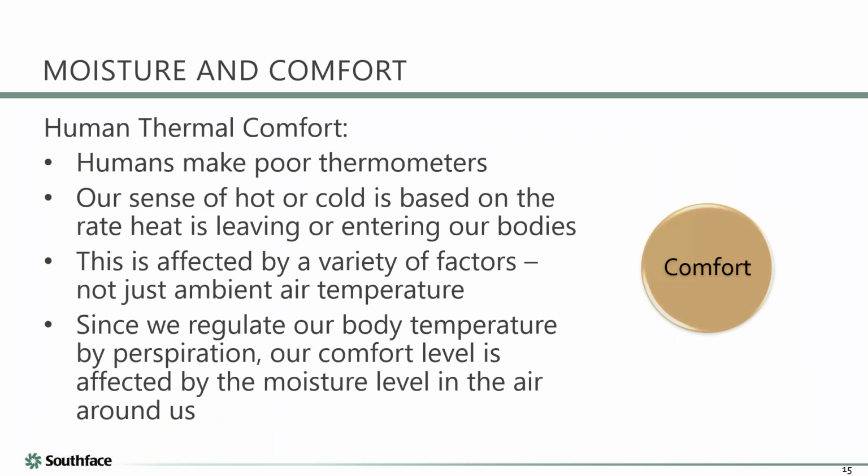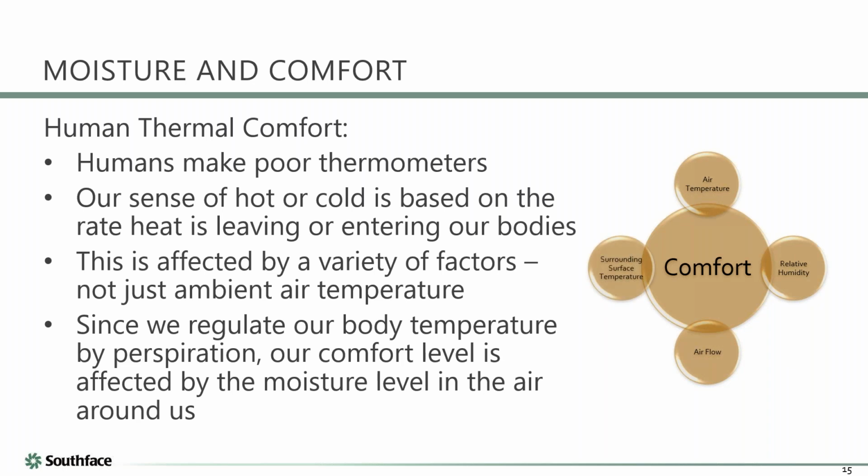What affects comfort? Not just temperature, right? Yeah, so we think of temperature, obviously that's what we see on the thermostat, but it's much deeper than that. Something that's near and dear to our hearts down here in Atlanta, Georgia, is the relative humidity. Higher humidity levels prevent us from adequately regulating our body temperature through sweat, so that in turn makes it feel more uncomfortable. Also airflow: if you're standing under a fan, that's going to help with that sweating process, and it's going to help you feel a little bit cooler. And of course, fans only really work well if you're standing by them or under them.